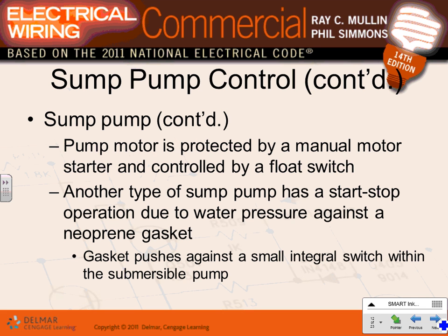Okay, sump pump. So they talk a little bit here about the sump pump, guys. It has a manual motor controller, and a floating switch controlling it. So the floating switch is really mechanically closing and opening contacts in the control circuit of that pump to turn it on and off.